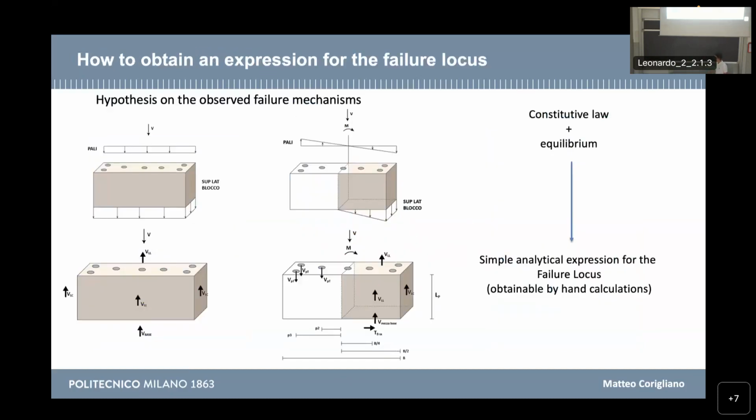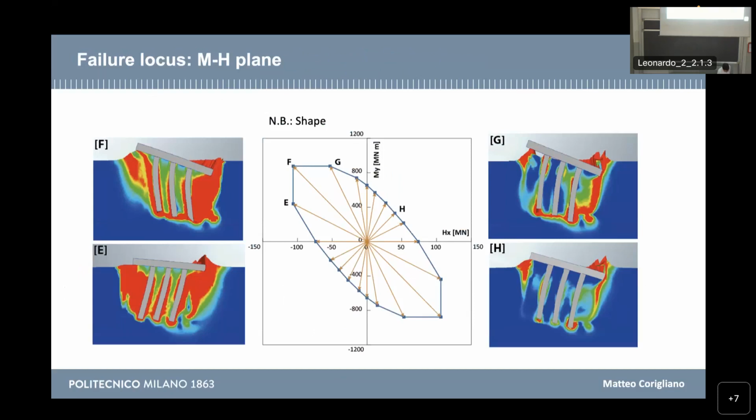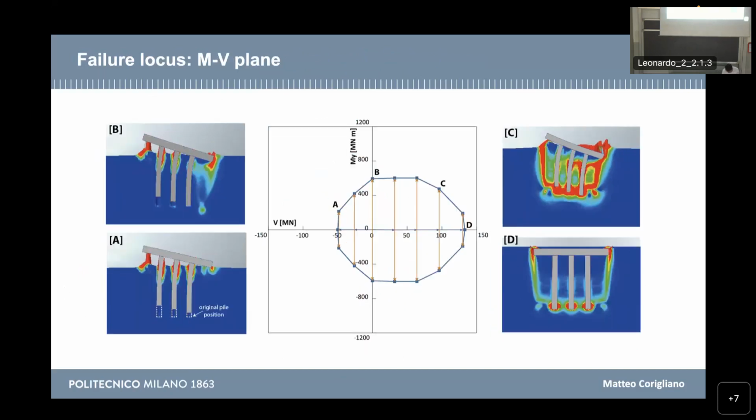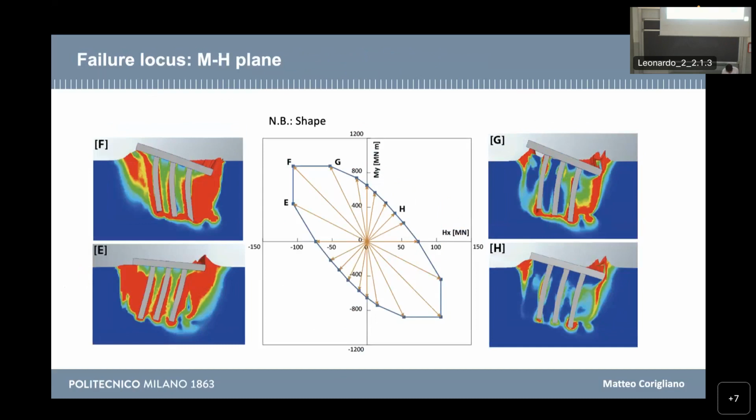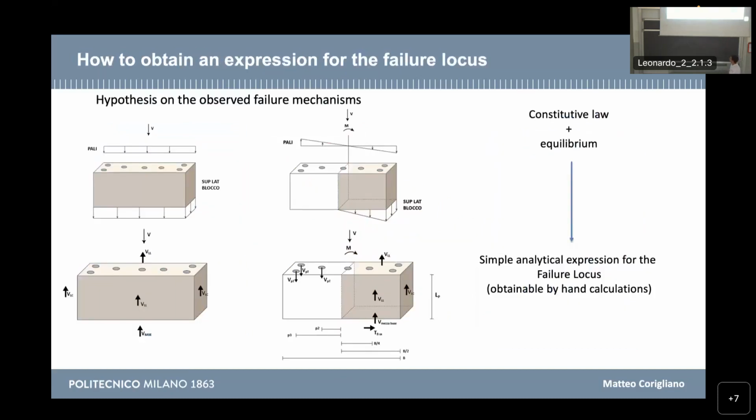And observing the mechanism happening at the foundation level, I try to propose simple expressions, a simple way to recover the shape of these failure domains, this failure locus, by means of equilibrium and imposing the constitutive law.